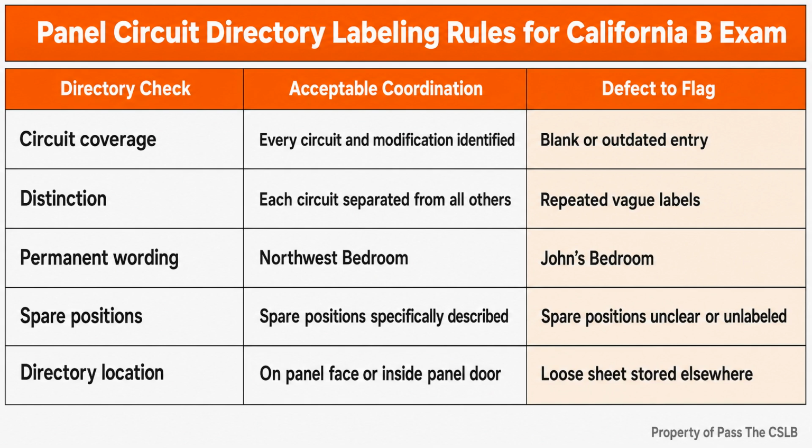Circuit rating awareness starts with restraint. A general building contractor needs enough knowledge to notice a conflict, but not to turn a coordination check into an electrical design exercise. If the plans identify a dedicated circuit, the panel schedule should identify that circuit clearly. If a circuit has been added or modified, the directory should be updated. If the installed breaker, the equipment information, and the approved documents appear inconsistent, I stop and coordinate a qualified review. I do not solve that conflict by choosing the next larger breaker.